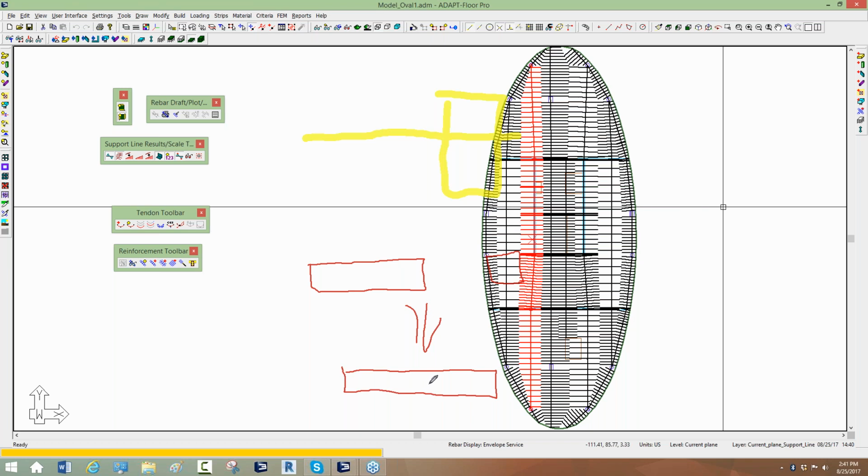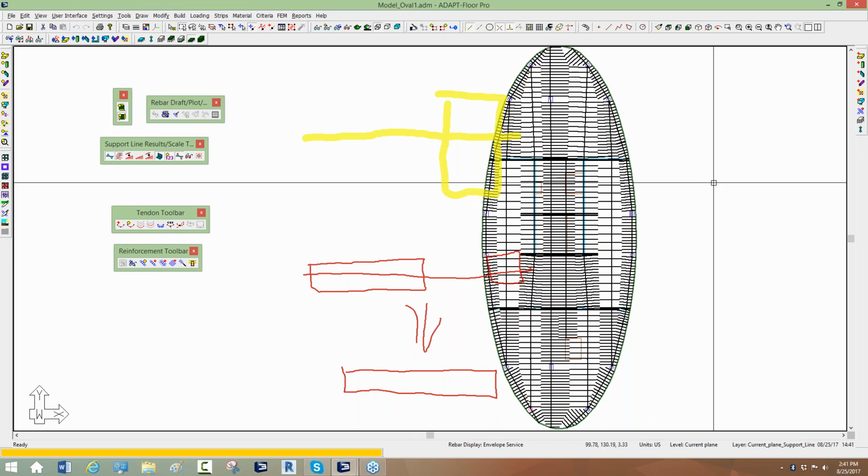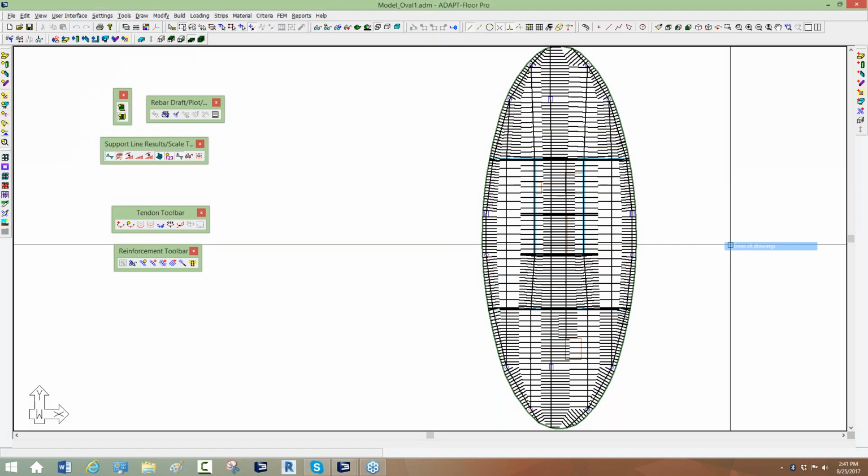And so when it calculates reinforcement and checks stresses for this section, it assumes that it's a combined section, and it integrates the nodal actions for shell or frame elements representing these slabs, or in some cases beams, for this design cut, which can lead to an inaccuracy in the result. So in that case, we would want to have a splitter, and I'll quickly show you.